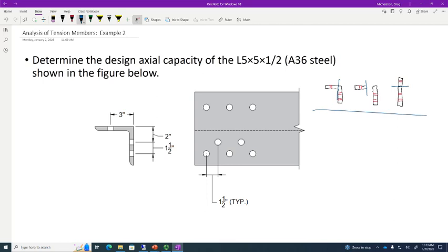you all know by now that steel design is a science that involves a lot of lookups. So let's start off with the simple stuff. Start off with A36 steel. Got to break out your AISC 15th edition steel construction manual. Go to table what? 2-4 on page 2-48. We got to look up the FY and the FU for steel that's grade 36.